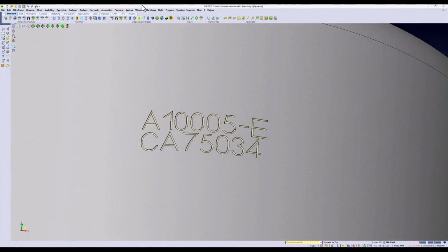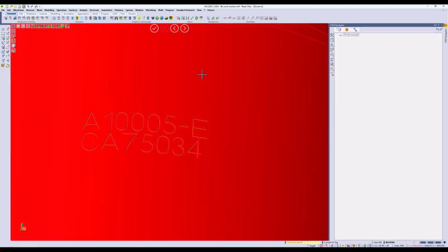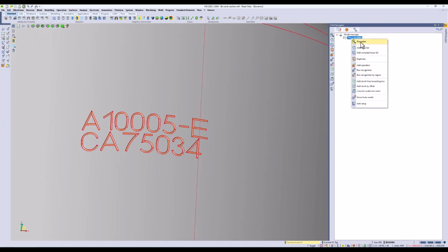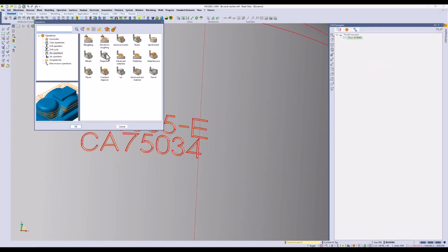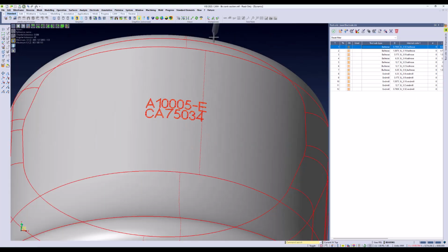So now let's do some machining off of this. I'm going to go into Cam Navigator. I'll add a model into this area. That model is going to be used for 3-axis work. And inside of this piece management, I can look up my 3-axis machining. From here, I will select the projection command. Projection is used specifically to cut a profile or cut right on a line to create the engraving text. I'll select my tool for engraving.